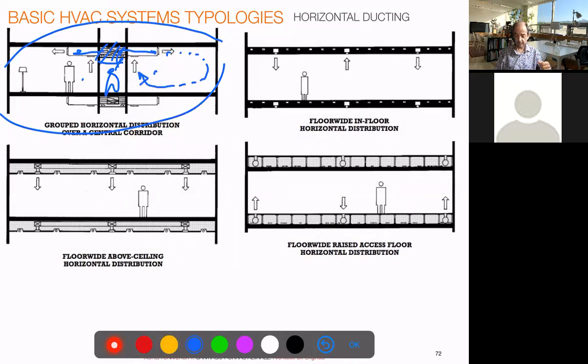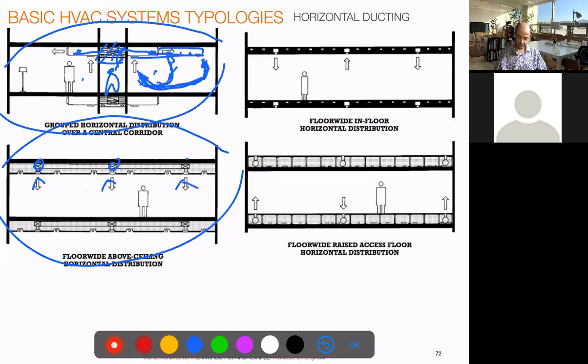If the diffuser is more in the end, you will have much better movement of air, or with more elements, more diffusers, so you have more regularity, but you have to make sure the air gets well distributed through the room. Another very common system is the more divided area by individual ducts and then having plenty of diffusers in the whole room. Again, you need to design it in a way that the air is collected probably by a lower duct or some area or the ceiling. So the air is moving through the whole room.